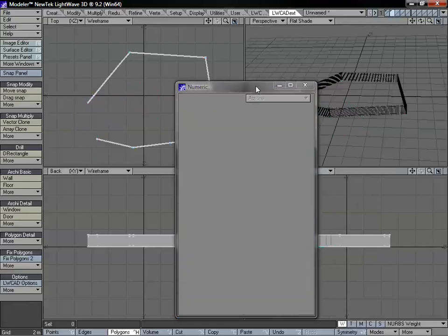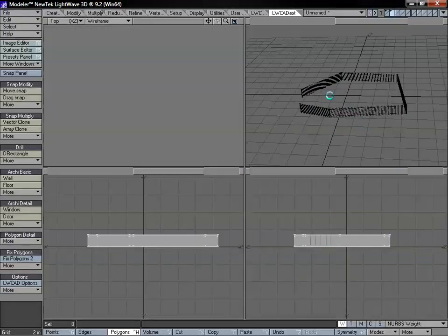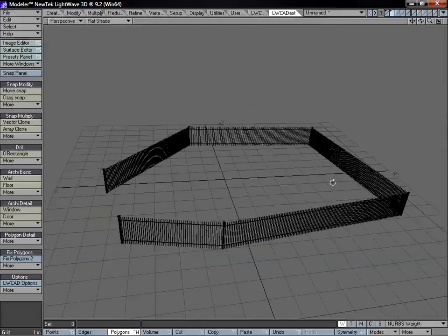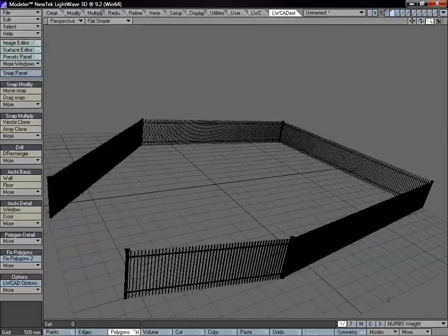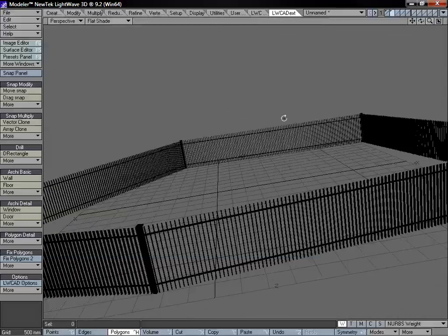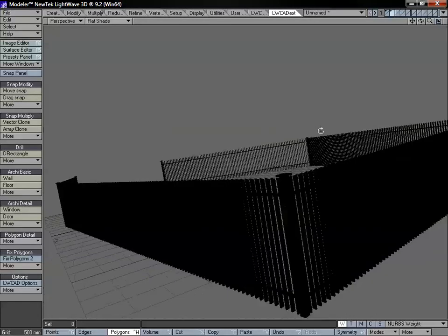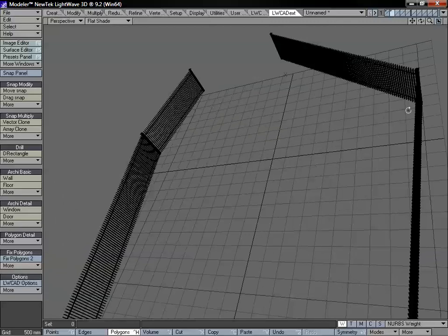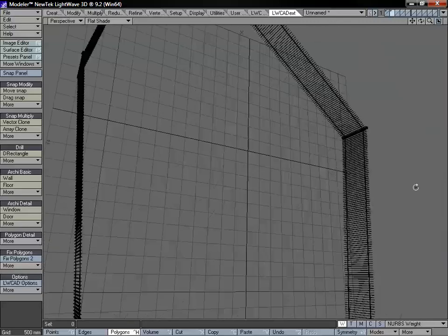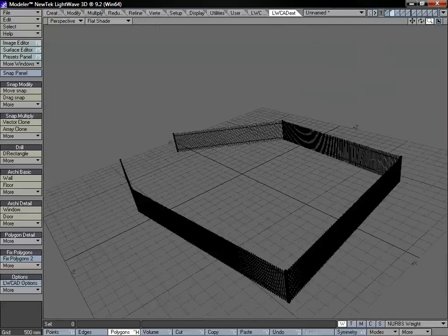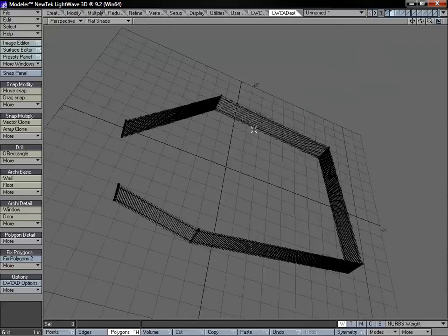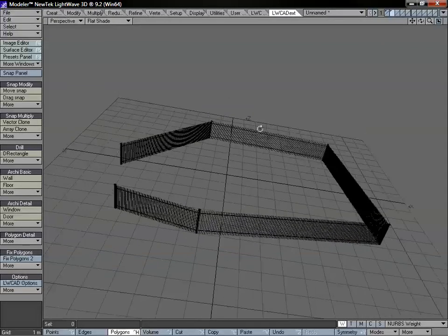And I'm just going to hit the spacebar and end that for right now. Open this up in the perspective view, and we can see this a little bit better. And you can see we have a post selected in every single area that we created an endpoint. Now what we could also do is select create points and in between values and set exactly where our posts are going to be.